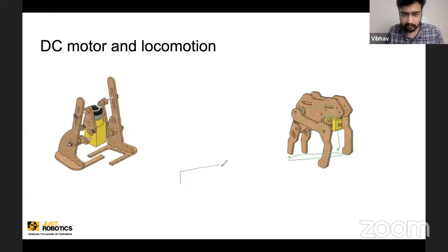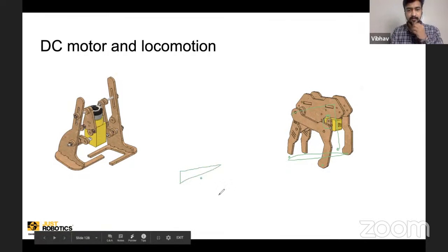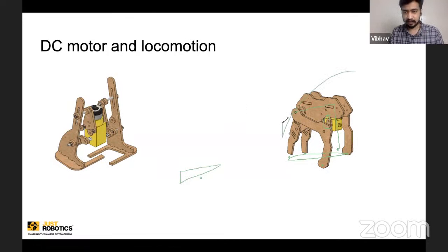So you get a very narrow point like this, and the robot CG is here. So the robot will tip over. It will fall like this to its right. When the right forward leg is up, the CG of the robot falls outside these 3 points being the contact polygon. The robot falls. So how I was able to solve this is by increasing the width. Wait, I'll take a different color. By making the robot a little wider, now I have this.